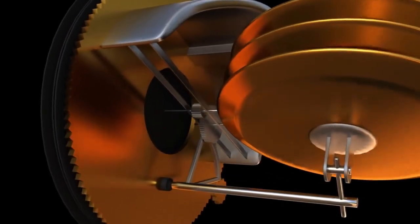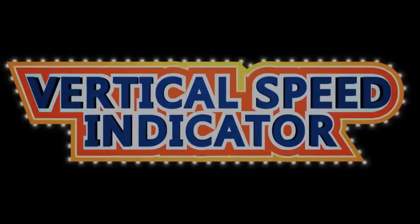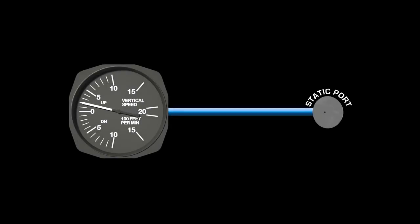The realignment is accomplished by rotating the entire inside mechanics of the instrument. Vertical speed indicator. Another instrument that uses only the information from the static port is the vertical speed indicator, more commonly called the VSI. The VSI measures the vertical speed of the aircraft in terms of feet per minute.